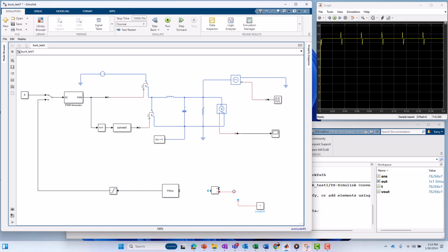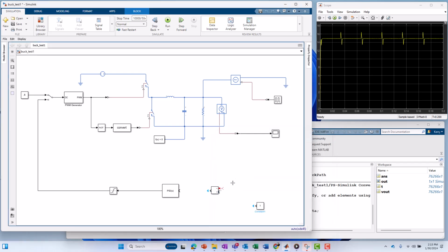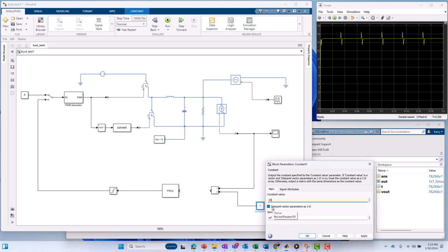You could say, well, this is going to be negative feedback, so I'll just connect that there, and the reference voltage goes here. But then you get these crisscross wires. It's not as pretty or intuitive. So let's not do that. Let's just change the ordering of the signs. Instead of plus minus, we'll go minus plus. Negative feedback always. Okay. And we're going to call our reference voltage 15 volts.